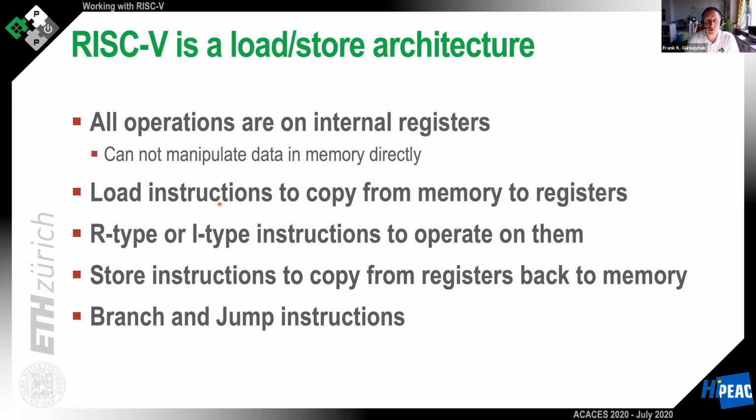So all operations, that means that all operations are on internal registers. There are no operations that manipulate data in some memory address directly. What you need to do is you need a load instruction that copies from memory to registers. Then you have your other instructions, you add it, you shift it, you XOR it, or do whatever you want to operate on the values that you copied from memory into registers. And then you have store instructions to copy from the registers back to memory.